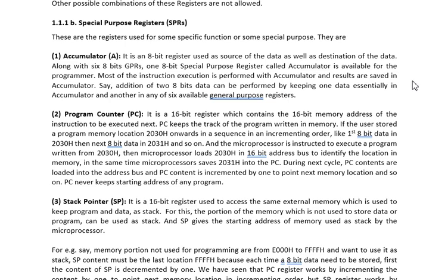So these are the 8-bit data, and 16-bit data will be 0000H to FFFFH. These are 16-bit. So memory location starts from 0000H, and it can go up to FFFFH. That means 64K. We'll talk about memory and how memory size works, everything, in the memory chapter. That will be covered in another video.